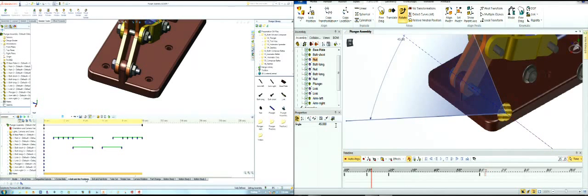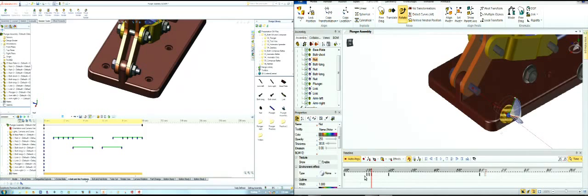And what's really great is you can type this in. So let's say we want it to rotate 270 degrees. When I hit enter, watch what happens on my timeline down here. It interpolates in between that. So it puts key points as it goes through, so you don't have to manually go through and say rotate a little bit, move, rotate a little bit, move. It just understands that that's what needs to happen. So from here to here, it actually rotates while it's, yep, there we go, while it's moving out. And you would just repeat that process with all three.